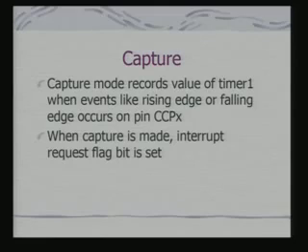Now, this is a very interesting feature. You are actually recording events, and you are recording events with respect to time. This kind of feature is not commonly available in other processors. You must not have encountered it when you look at a general purpose processor like the 8085 or 8086. It is provided here because this is supposed to take care of various external events interfaced with the external world. So it can keep track not only of the event, but also the time, in a sense relative time based on the timer count when that event has occurred, and that value is recorded in the capture register.